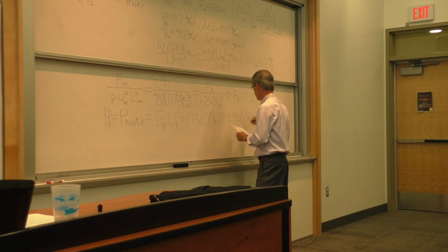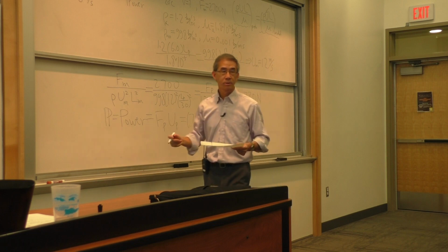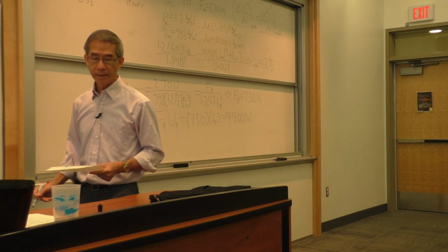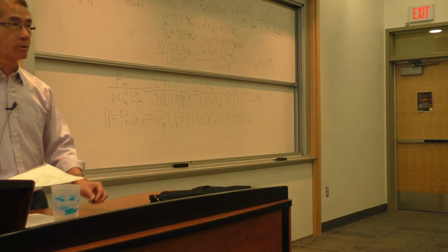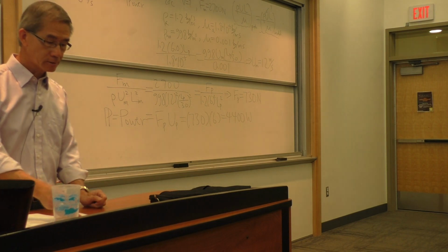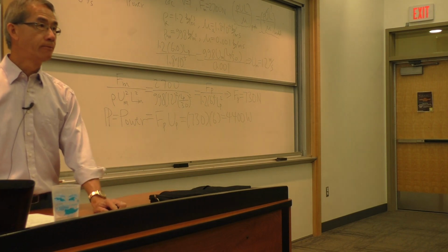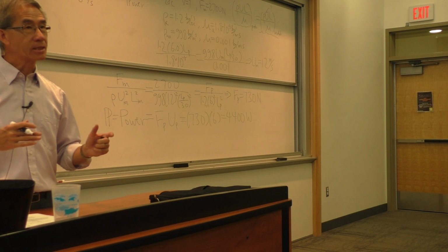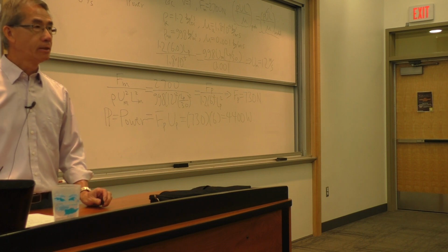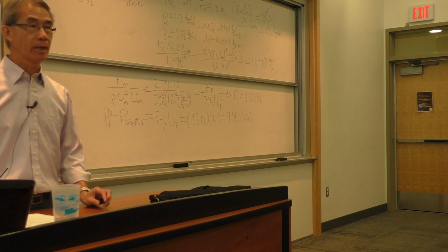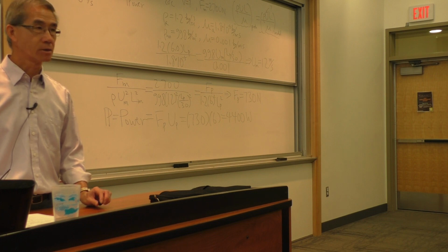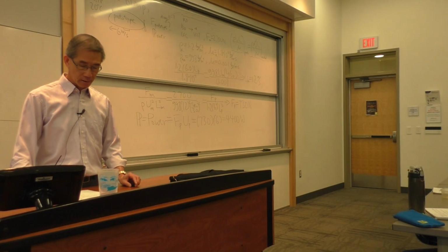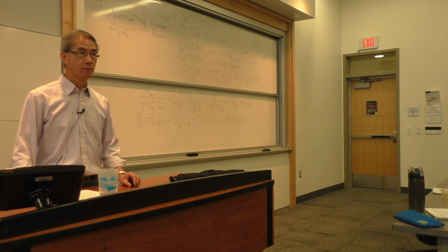So it's about 7 kilowatt, which is reasonable, not too big, because you're not moving very fast. It's basically just a balloon. So for a very limited low-speed application, I managed to match all the pi terms. But again, I emphasize, your homework will show you it's not typical. Okay? Do you understand the concept of this similitude? Okay, very good.